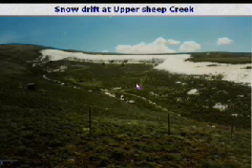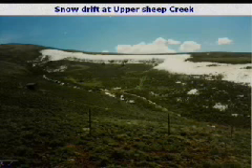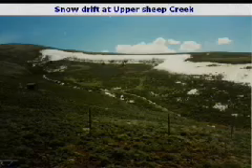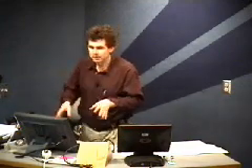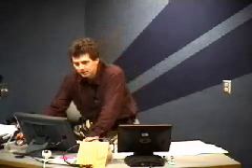The approach we took, I mean, there are wind-blowing snow models that have been developed, and I've collaborated with people sometimes on trying to do that. But the first approach we took here was, the idea of trying to model the wind processes was rather complex. So we said each location has a certain propensity to accumulate snow. If it's in a place where drifts form, that propensity is large. We're going to quantify that with what we call a drift accumulation factor.